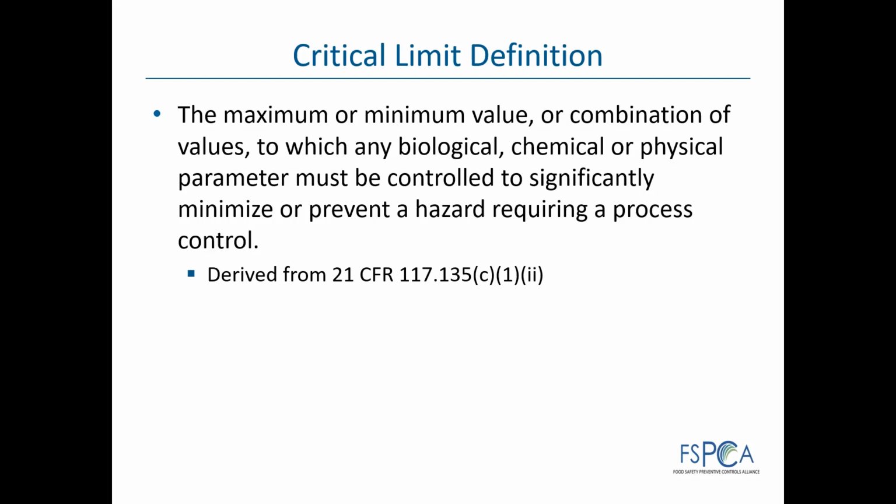First of all, I want to say about this parameter, we talk about biological, chemical, and physical. Most of the time, in 95% of scenarios, we talk about chemical and physical parameters. Biological parameters are mentioned rarely. The most frequent one is the zero tolerance of coliform and fecal coliform in the drinking water system or some beverage products. We do not mention biological parameters too often. The reason is that rapid testing for microorganisms is getting there, but has not been commercialized for every place in the world to use in these types of regulations and standard procedures. So we are talking about chemical and physical parameters.